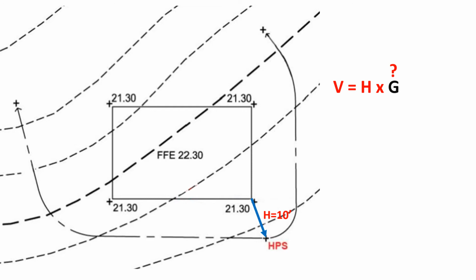It creates effective drainage and doesn't affect the use of that area, right? In addition, you will need to pay attention to other slope requirements that are given to you. For instance, in our exercises, there is a requirement for maximum 5% slope for the first 10 feet away from the building. Okay, so with all that said, let's set the slope as 2% as a start.